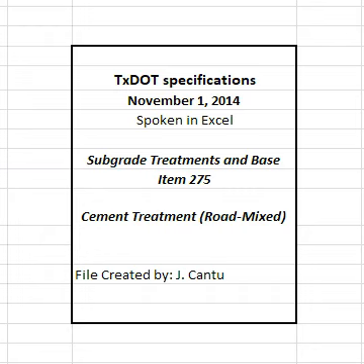2. Materials. Furnish uncontaminated materials of uniform quality that meet the requirements of the plans and specifications. Notify the engineer of the proposed material sources and of changes to material sources. The engineer will verify that the specification requirements are met before the sources can be used. The engineer may sample and test project materials at any time before compaction. Use TxDOT for material definitions.